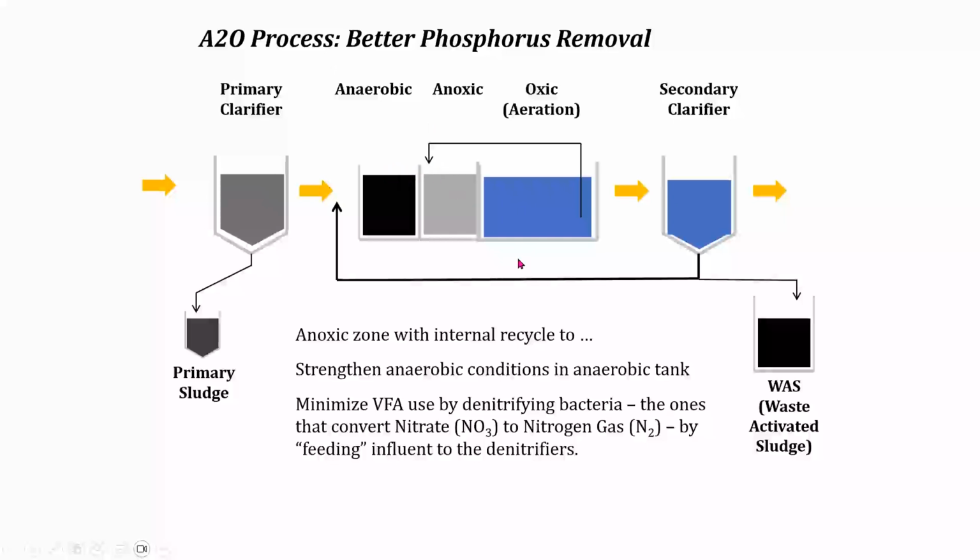In the example, does the primary clarifier remove too much carbon from the system that could be used for PAO growth? Generally, yes. Which is why your speaker here is not a very big fan of primary clarifiers. There's a treatment plant in Connecticut that I've been visiting over the years that has 2 primary clarifiers, and they've been offline for maintenance for about 6 years now. And because they're out of service, there's more BOD coming. That plant does not have an anaerobic zone, has an anoxic zone. And that extra BOD has helped significantly with the nitrogen removal.